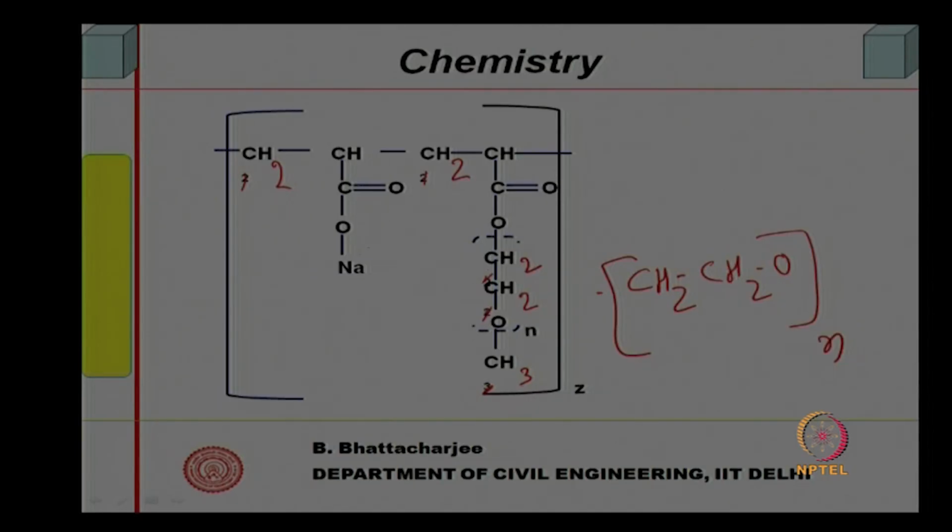So, there is an ether here, this is the polycarboxylate, sodium carboxylate, so sodium is there in the acid, and in this one instead of sodium there is another ether polymer, copolymer. So, there is a copolymer here. So, you can see this is sodium, this will get dissociated, this will attach to the cement particle, but this one, this branches where there is a polymer, copolymer, this will remain outside, in the sense that this will remain attached to the branch.